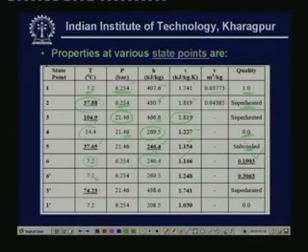And point 6 dash is for the SSS cycle without liquid suction heat exchanger. So, here again the temperature is 7.2, pressure is 6.254, and the enthalpy here is the enthalpy at the exit of the condenser, that is 269.5. Again from the enthalpy value and the pressure you find the entropy value, and you also find the quality, which works out to be 0.3063.